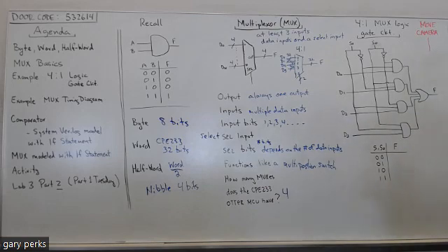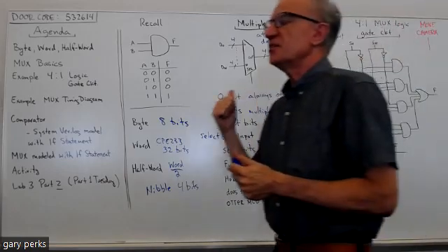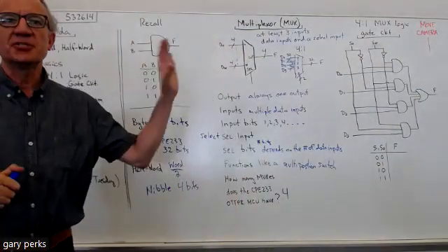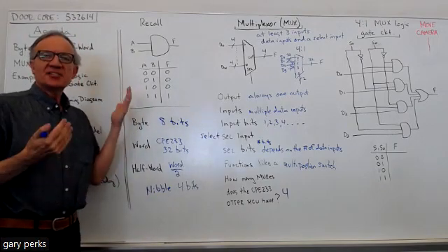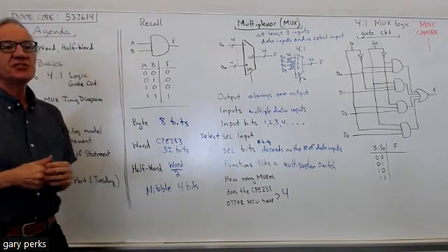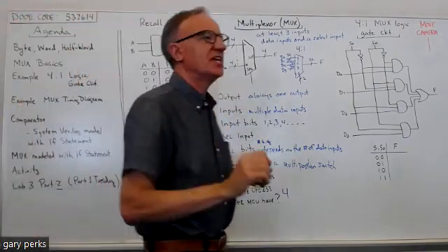Remember how we had an activity on that? Use a NAND to make a NOT, a NAND to make an AND, a NAND to make a NOR. And you can take a NOR and make a NOT gate out of it, or an AND gate. So yeah, AND gates are not universal. Only NAND and NOR are universal. Now, the other thing you might remember when we were talking about universal gates is that I talked about how it's important to be able to understand a truth table.